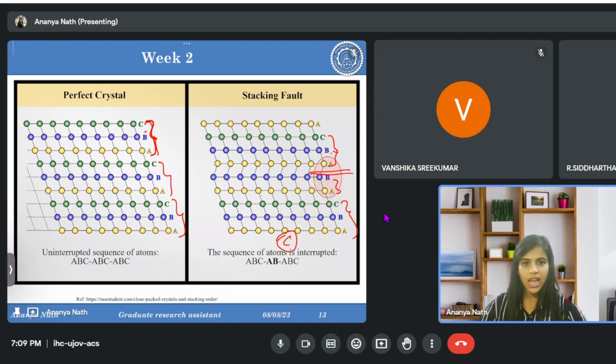The parent atom will have a particular type of electronic configuration, and the solid atom will have a different one. So due to this dipole, if the dislocation finds a positive end to be a preferable side to move, and the solid atom is introducing some negative end, then while moving through the lattice, with both positive and negative ends present, the dislocations cannot move very freely. So we are disrupting the path.